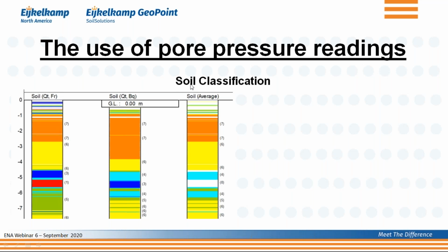And then the second one is a function of the tip resistance and this BQ, the pore water pressure parameter. You see that those two don't necessarily always completely agree, and quite often people take an average to get an idea of what kind of soil we have.